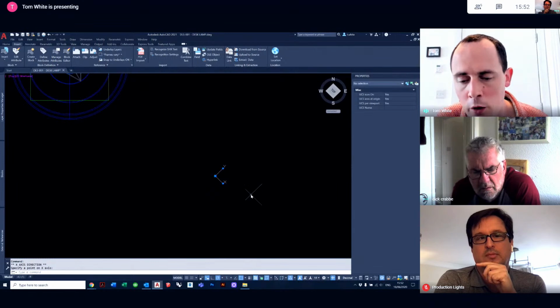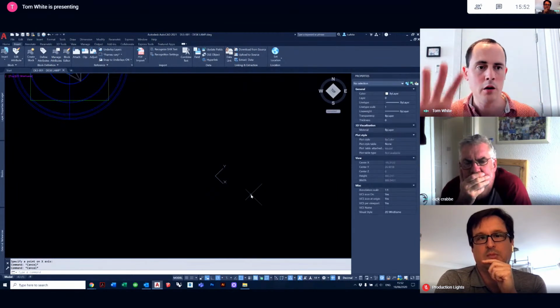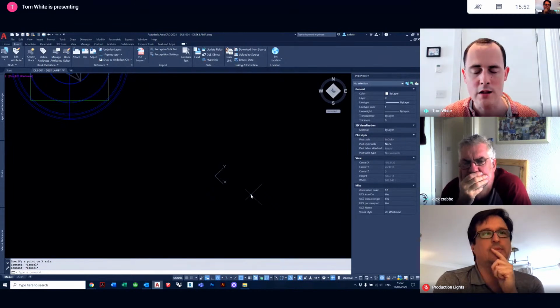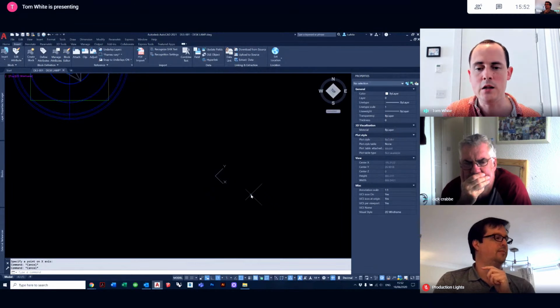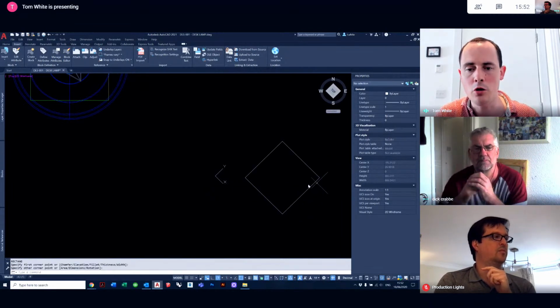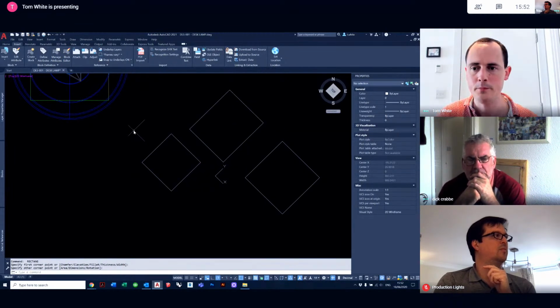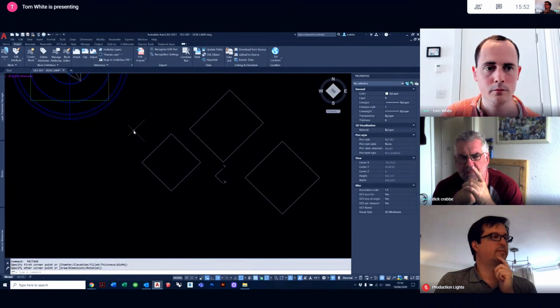And you'll see my cursor has changed. So therefore, I'm in 2D plan view. I'm looking in plan view, which is why you can't see the letter Z, because the letter Z is towards me or away from me. And I can do a rectangle, and anything I draw is going to be starting on that 45 degree angle. Gotcha.